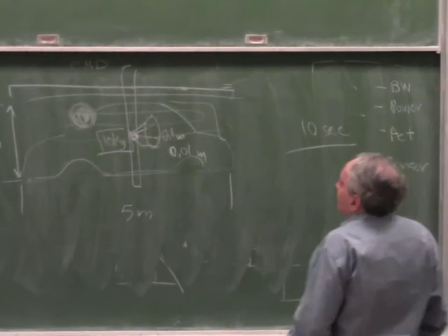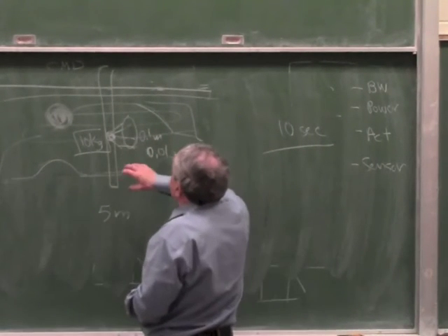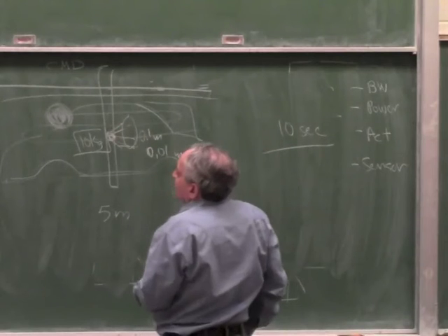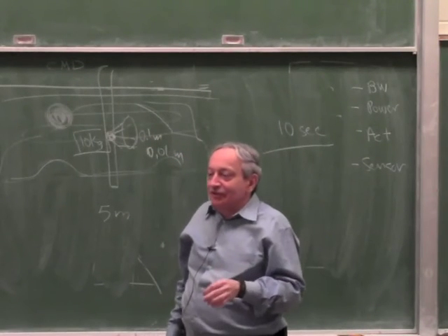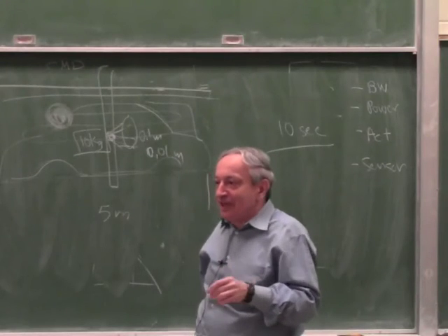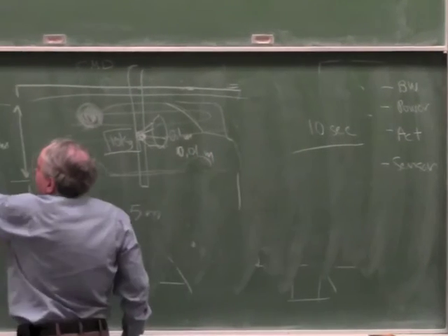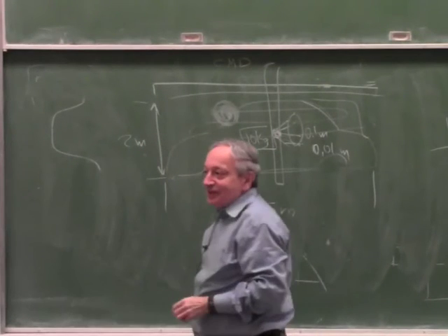Good. So if this is 2 meters, I have to cover 10 centimeters, okay? So I need at least 20 scans. If you are a good student, you will put a note that it's better to use 25 scans, because if you think of a spray gun, it's probably a bit like this, right?